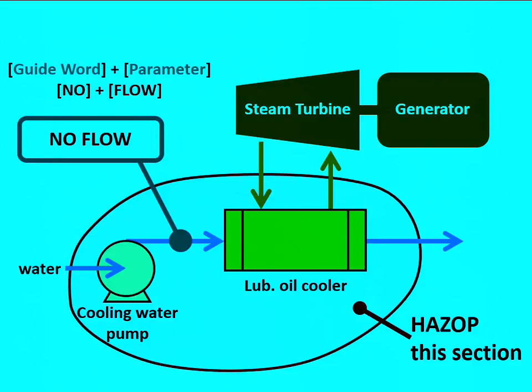It's pretty obvious, isn't it? Pump stops, yeah. Is it possible for the pump to stop? Yeah. Anybody who's worked with pumps knows, yes, of course it is. Any other causes for no flow? Inlet block. Well, we're not sure about where this water's coming from, but it could be a river, for example, so it would have a filter, strainers, and if the filter got blocked, yeah.